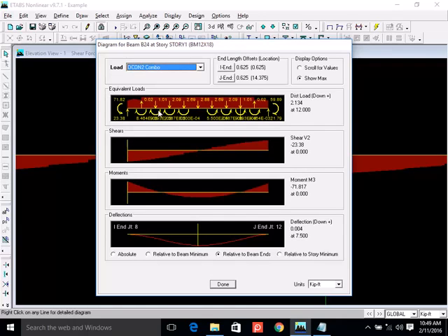You see these point loads and moments at several locations. These are actually points where the slab is connected to the beam. In real life the slab is continuously connected to the beam, but in our case the slab is connected to the beams only at the points where we have mesh, right? So that's why at every meshing point you have these point loads.